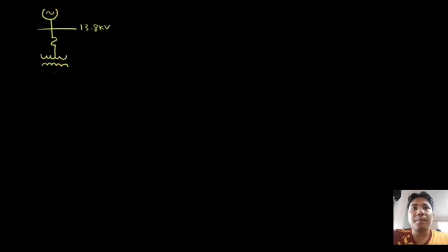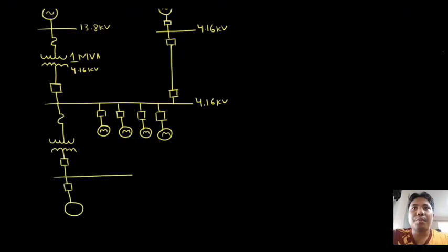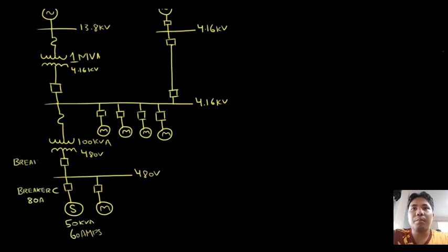To explain this concept, let us again consider a facility with a 50 kVA, 60 amps static load as discussed in the previous parts. All breakers should be rated at some percentage above the full load amps of the downstream load breaker, C. C is rated at 80 amps at 480 volts. Breaker B is 120 amps at 480 volts. Breaker A is rated 100 amps at 4.16 kilovolts. The breaker amp rating is much greater when we compare all the breakers at the same voltage level.